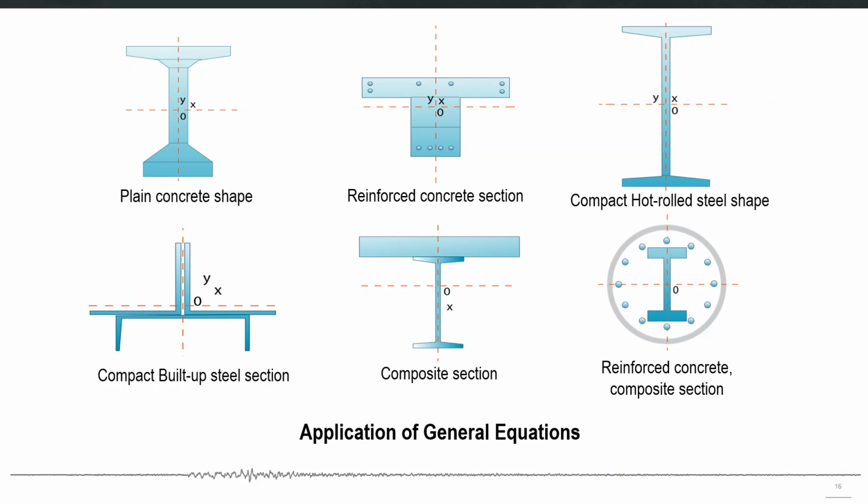And since now we have very innovative materials for the retrofitting of cross-sections, all we need to know is their stress strain relationships. For example, different kinds of fibers are being used to retrofit columns nowadays. If you have the stress strain relationships for those polymers or those special materials, you can model them in Section Designer and get the overall sectional response.